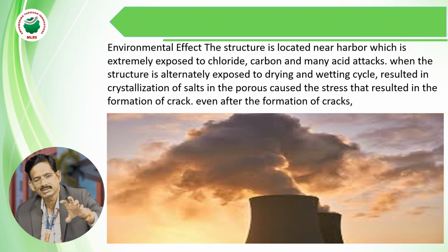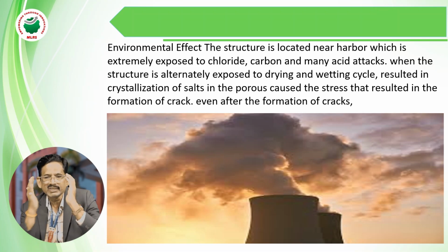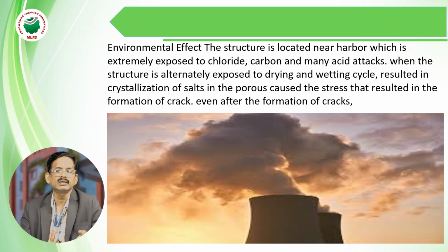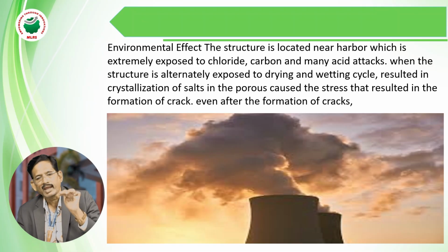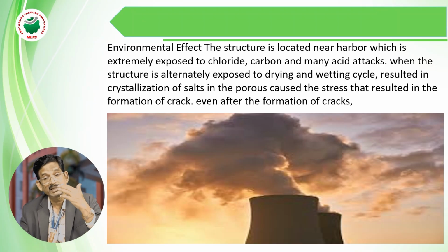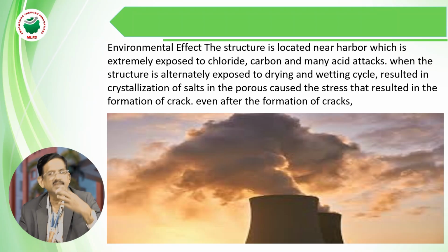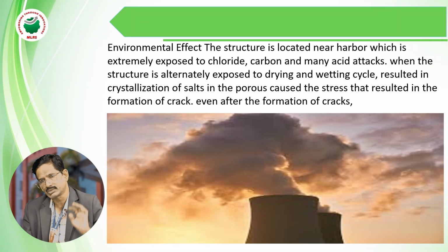If this concrete is subjected to chloride contents, we have to see whether these are within permissible limits or not. That is to be done with the help of the rapid chloride permeability test, RCPT. In RCPT, we are passing electricity through the concrete cube. We have to see how much chloride content is present, okay, and many acid attacks also.